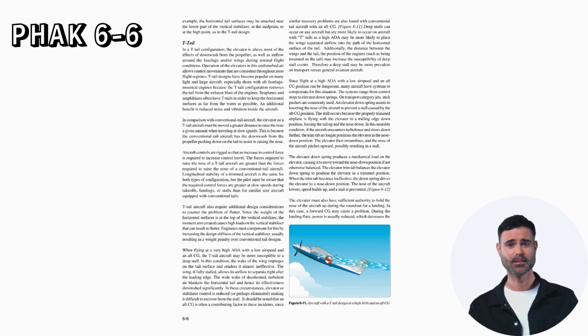T-tail. In a T-tail configuration, the elevator is above most of the effects of downwash from the propeller, as well as airflow around the fuselage and/or wings during normal flight conditions. Operation of the elevators in this undisturbed air allows control movements that are consistent throughout most flight regimes.